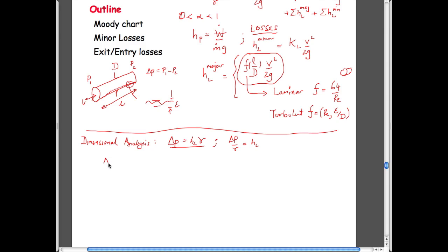So in terms of dimensional analysis, we could write it in terms of all the variables that would define our system. I won't use squiggly f because we've used it up here. So a function of, what are the variables that describe our system? Well, we have a velocity of fluid that's moving along our system. We have fluid properties, which would be density and viscosity.